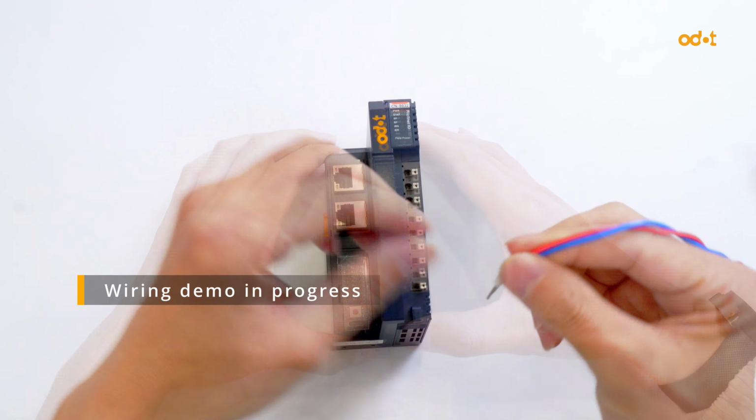So now, let's set the device name. In the device section, find the network card for the adapter. Double-click to search for accessible devices. Our network adapter's dip switch is set to 2. You should see the CN-8032 with the suffix -2. Select the network adapter. Now let's configure it based on the name we just found.